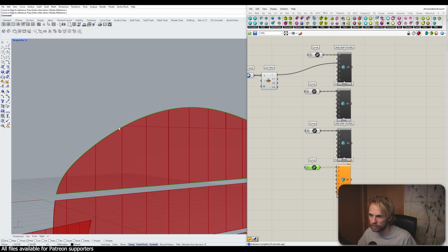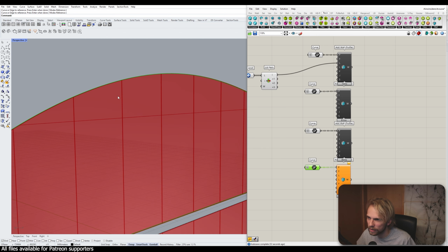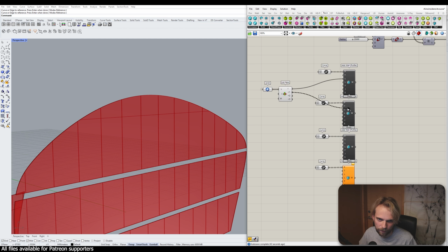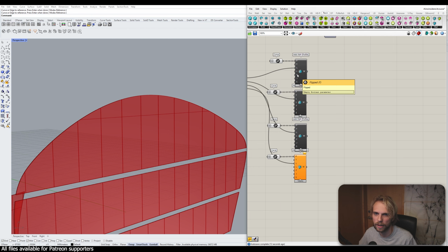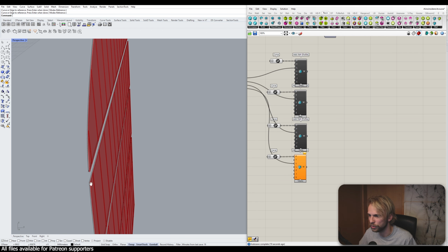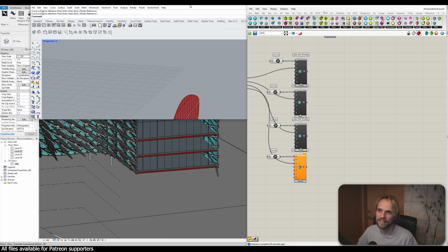I'm very curious to see what... Yeah, this seems okay. I mean, not great, but it's fine. And there's the glazing and whatnot, and of course you can add stuff later in Revit. Why is this complaining? Line sketch slightly off. Yeah. Okay, level 2, level 3, level 4. Then we have location line. Apologies, I don't know what that means. I can't explain it to you right now. And also we have, is it flipped or not? So basically from this profile, to which side does it go, right? Also, why is there a slight offset there? Whatever. Let's look at it in Revit.